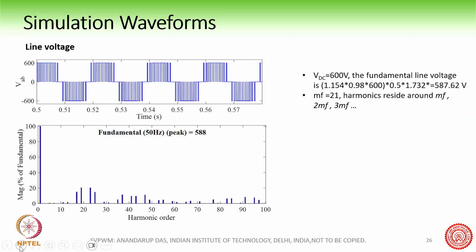But since it is a common mode voltage, in the line voltage it will go away, right? In the line voltages, which we have now shown, all these triplen order harmonics disappear. There are no triplen order harmonics anymore, because in the line voltage VAB, we will have VAO plus VCM, minus VBO plus VCM.